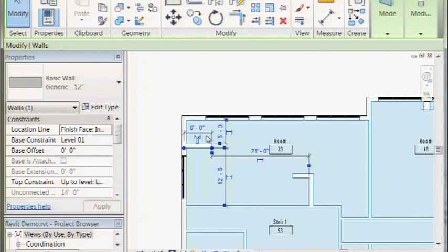This could potentially be a half wall, or there could just be a sink back here. This is not necessarily going to severely impact all of your analysis. So you have to decide that this entity, when it runs through this room, is going to become a shading surface. It's not even being thought of as a thermal wall, because it's not bounding anything. It's just kind of a jog.